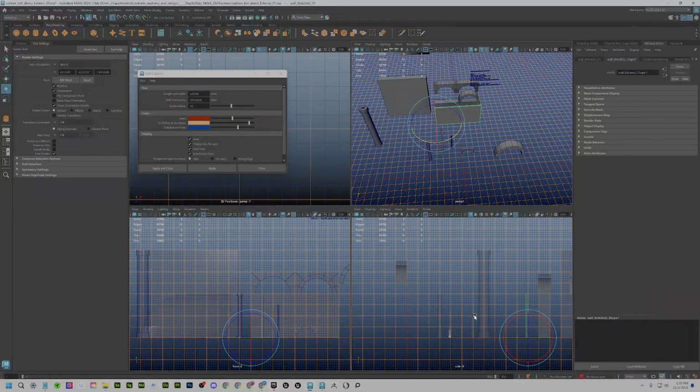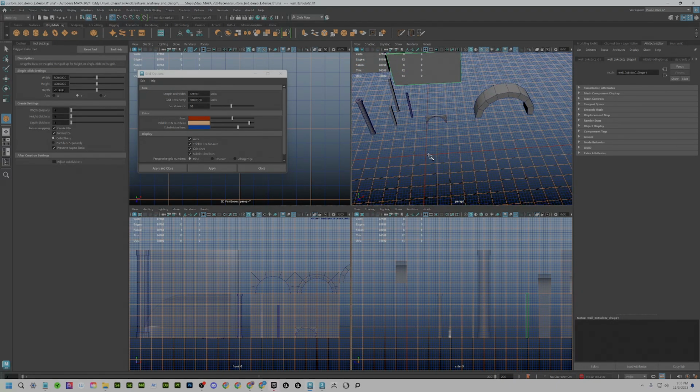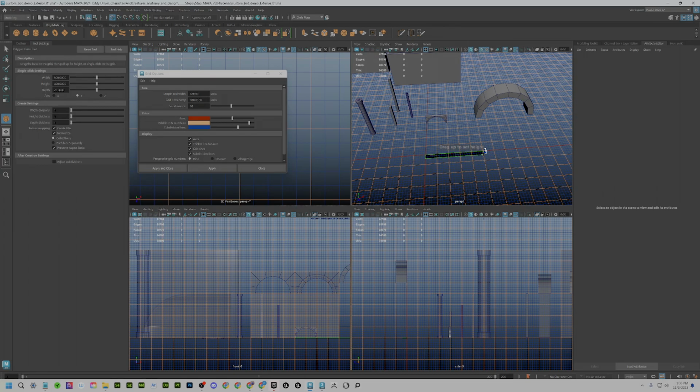So I go to my 4 viewport mode here, and I know these big lines here are every 100. So if I need to make my exterior wall, I'm going to go to the cube tool and come over here. And if I want to do a 400, there we go. And then make sure it's about 10 right there or 20 here. And if you're off, you can always just fix it very quickly and then let go, and then click and drag.